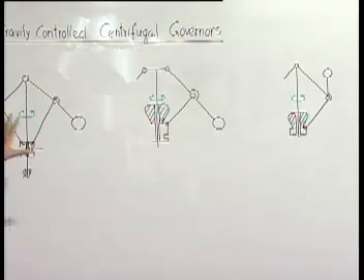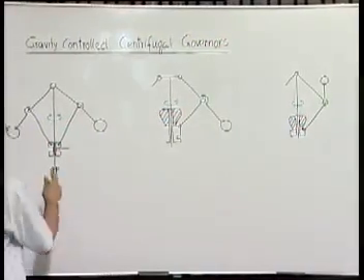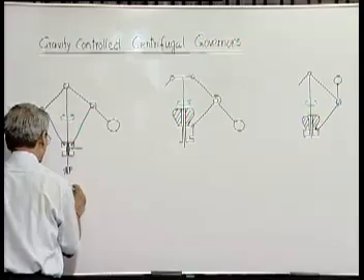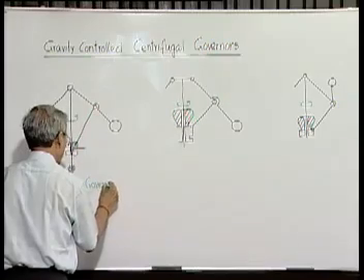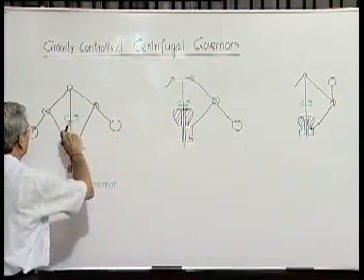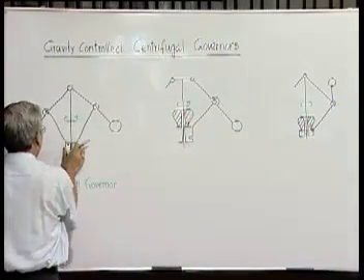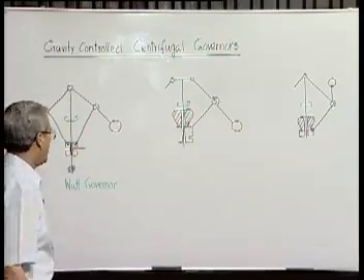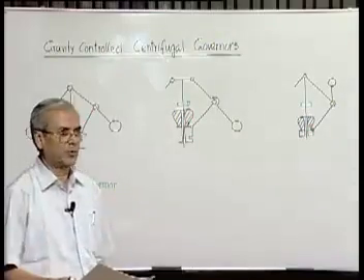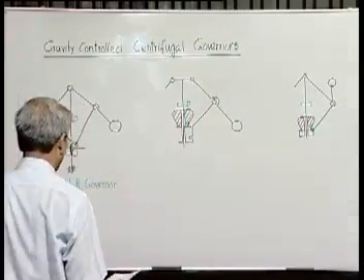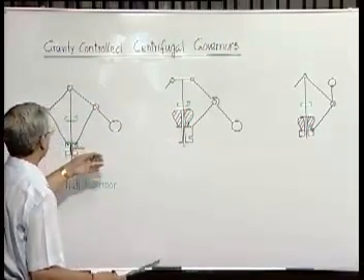These are the basic schemes of three different types of gravity controlled centrifugal governors. This is the familiar Watt governor, where these are the spherical balls which try to fly off when it rotates, and that tends to move the sleeve up and down, causing the lever which operates the valve mechanism to control the input energy or input power to the system or engine. A little variation of this, it has certain difficulties, particularly at higher speed levels.